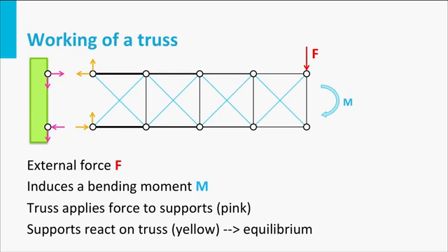In this figure, we can see the truss structure in equilibrium. The vertical force is countered by the forces from the support. The bending moment is compensated by opposing bending moments. Also, the horizontal forces are in equilibrium. In this truss, the elements like the bars and the wires connect the location where the load is applied to the support of the structure. That is what we call a load path. From this truss to a beam-like element is a very small step.